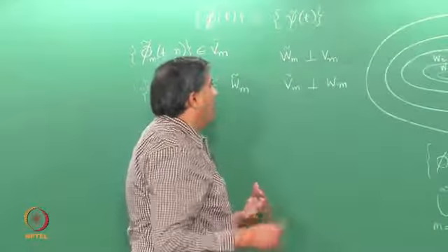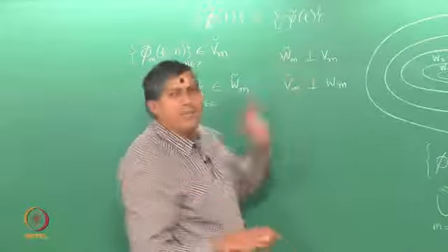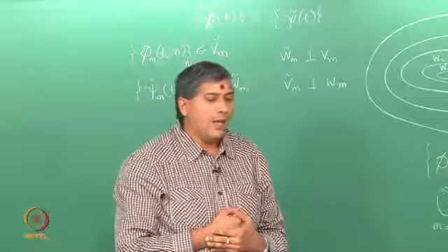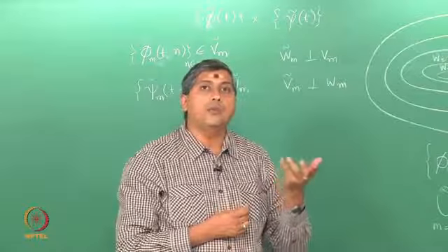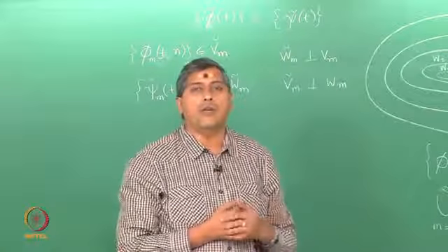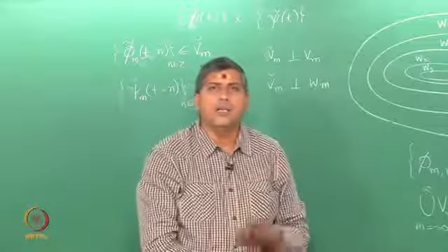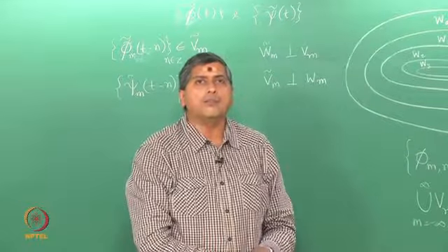Well, what this means is that there is a certain symmetry here in the reconstruction and the decomposition, and in fact this symmetry gives rise to what are known as symmetric wavelet filters. You can show that orthogonal filters can hardly be symmetric. Yes, you can design symmetric orthogonal filters.